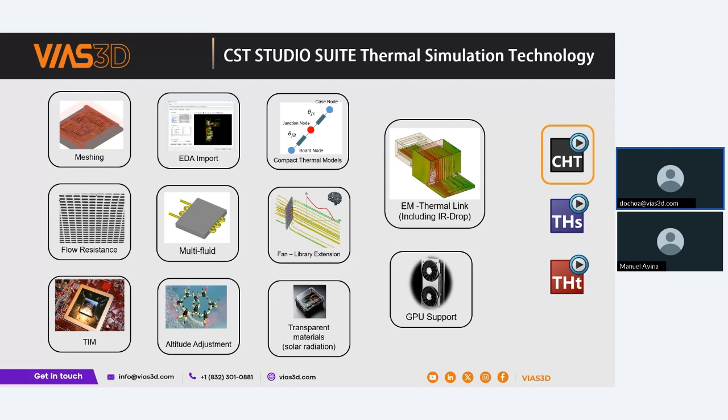That's also possible. You can simulate altitude effects. This is considered when you add a fan to your system for cooling. Those altitude effects will be there, and you can use thermal interface materials. You can even model a multi-fluid cooling system if you want to. Okay, and we will talk a little bit about that in a moment. Basically, the tool will help you build a realistic and efficient cooling simulation. Okay, all again in one single graphical user interface.